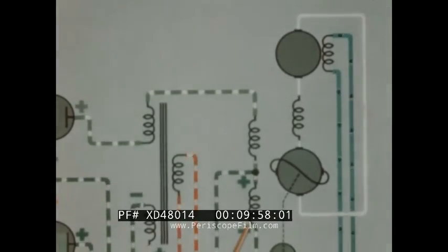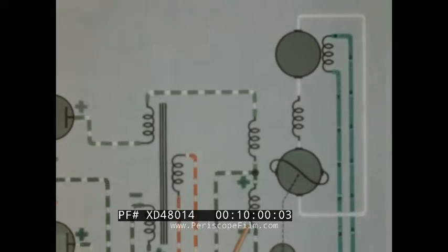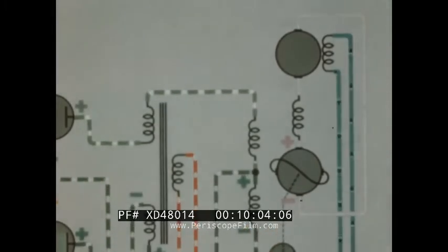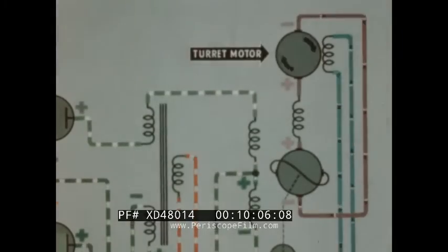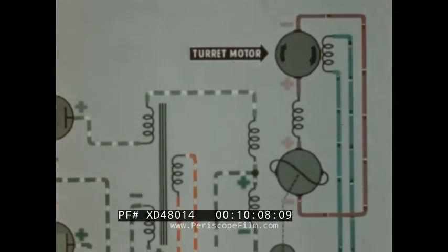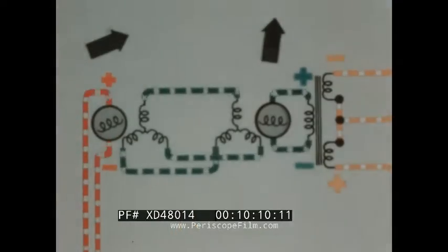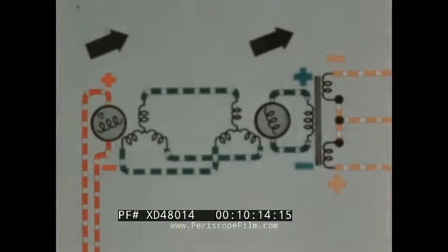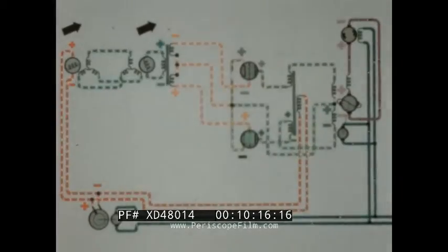The flow of current through the lower amplidyne field coil produces a DC voltage within the amplidyne generator, which sends a current through the turret drive motor armature. The rotation of the motor drives the guns and receiver toward alignment with the sight and transmitter.